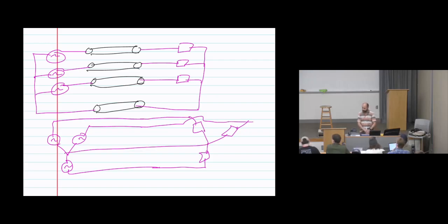Okay? So the top and the bottom are exactly the same, but I just make the shape so it looks like a Y. So this is called Y, or it's called star sometimes. It looks like a star or it looks like a Y connection. Some textbooks call it Y, some textbooks call it star. So this is the connection for the source. And how many conductors do we have? 1, 2, 3, 4. So star connection or Y connection can be used for a balanced situation.